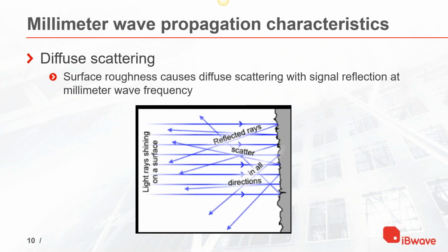And then the question is, why is there surface roughness at millimeter wave frequencies, and there isn't any being taken into account in, let's say, sub 6 gigahertz? Well, the reason is that it's the same wall, right? But it just seems to be rough. It looks to an incoming wave as a rough surface if the incoming wave frequency of operation is high enough.